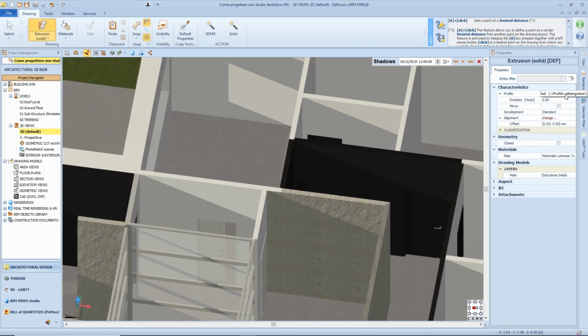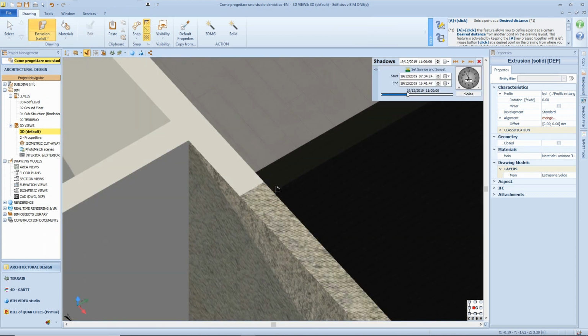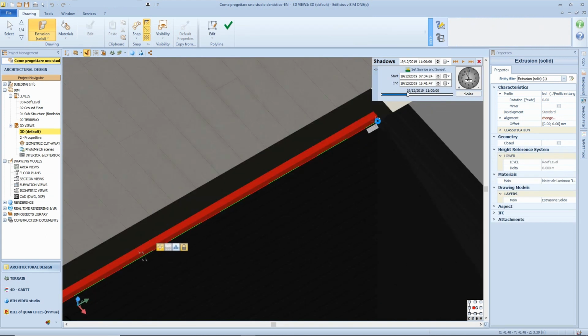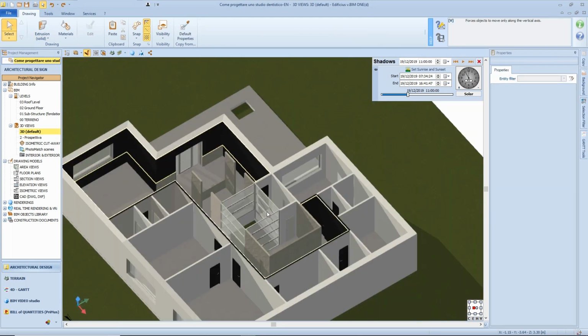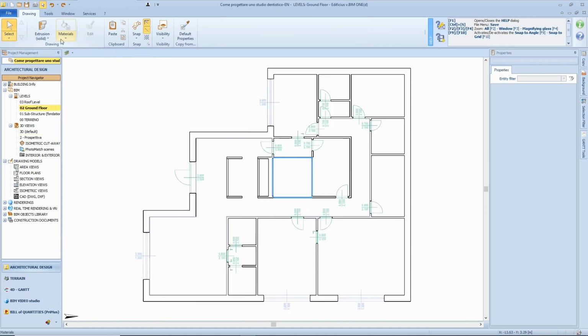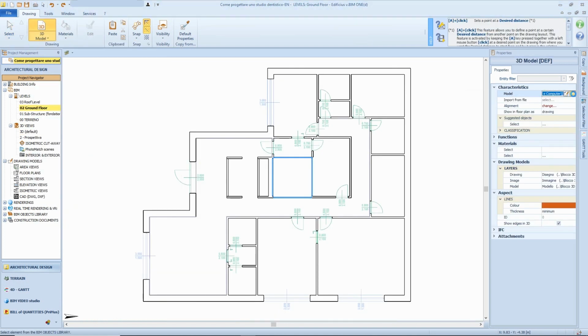We can now complete our modeling process by adding some other detail, such as our office furniture and strip LED lighting devices along the office inside the perimeter walls, achieved by using the solid extrusion object and setting the applied materials as emissive in the Properties box.